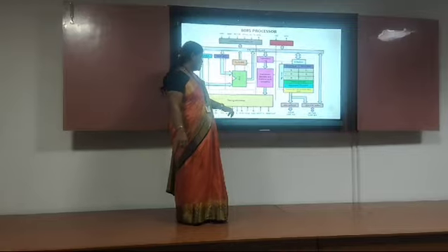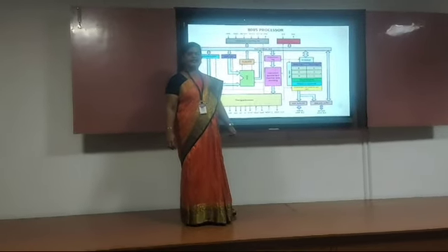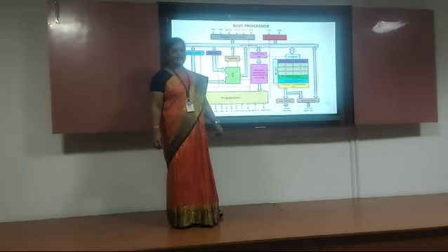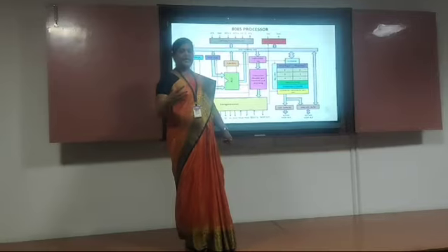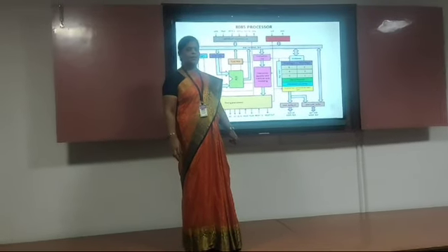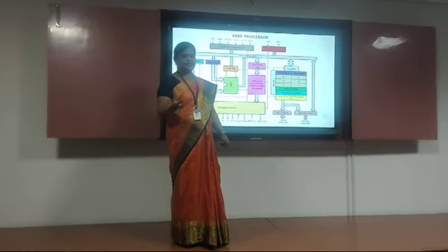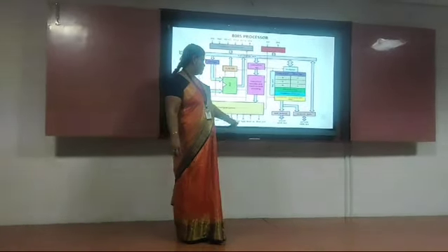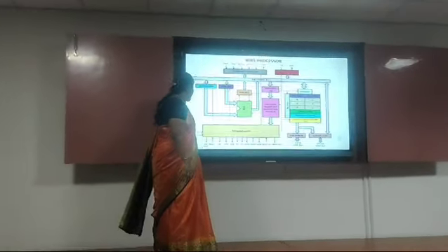Next we have hold and HLDA. Both hold and HLDA come under DMA, direct memory access. The hold signal means the external devices can use the processor's memory. So external devices can use the memory of the processors directly. Then reset in and reset out will bring the processor to its initial state. That is the purpose of this.